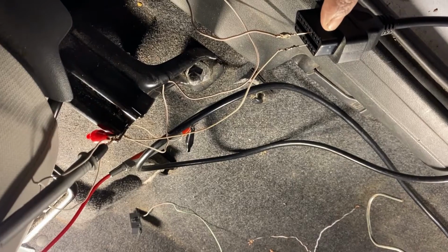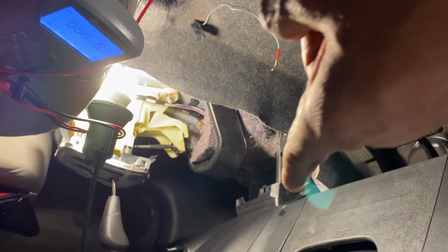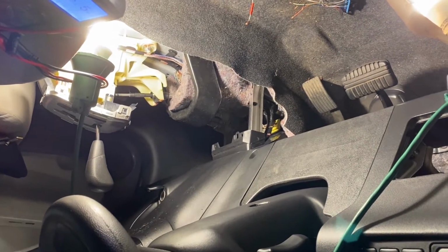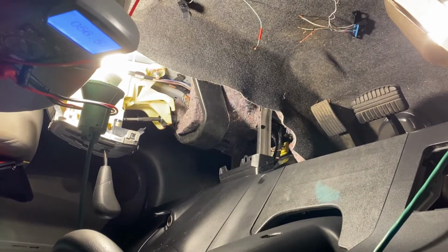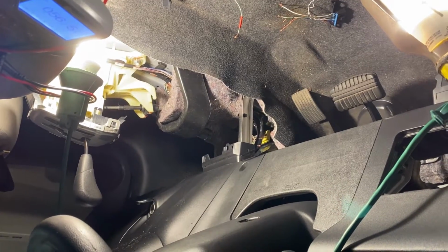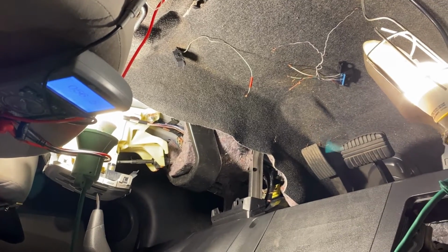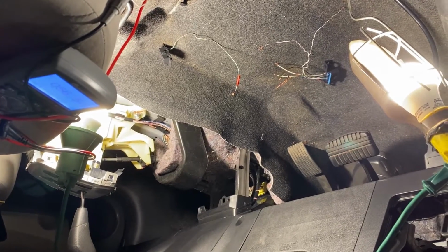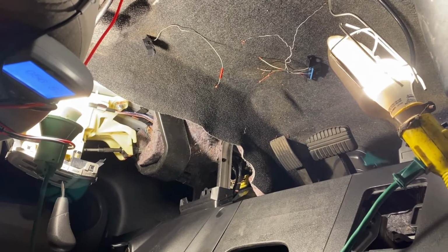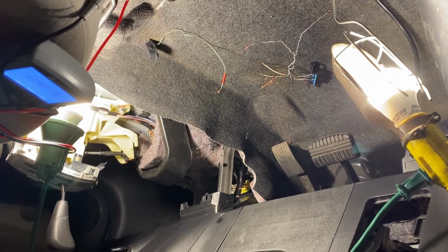So now we make sure the CAN bus is good, and I know it's good. So now our issue is with the airbag itself. Hopefully, if I can't get another calculator to dump the file in, I will try to find another module, but I'm still going to have an issue with the file. I used like 2-3 calculators to clear the file and compare it. But from my experience, I have a very good feeling that the dump file, when I cleaned the file, is the issue.